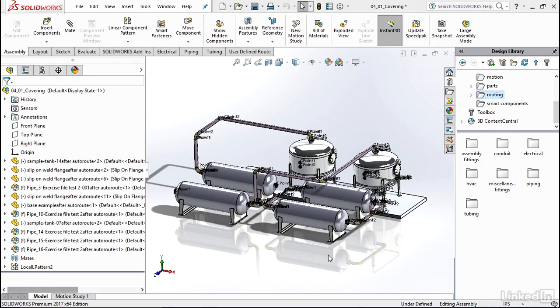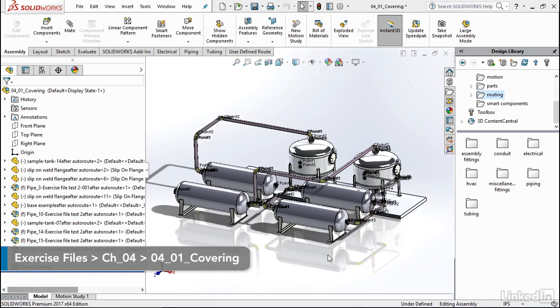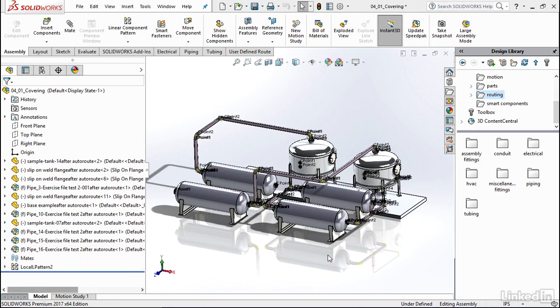In addition to editing pipe lengths, it might be necessary to add additional parts to the pipes in your route. One such example is a pipe covering that can include anything from rope to tape, but could be crucial to the design of your route. Adding this in SolidWorks can help you take into account spacing and weight of this covering. It'll also let you call it out in your drawings.